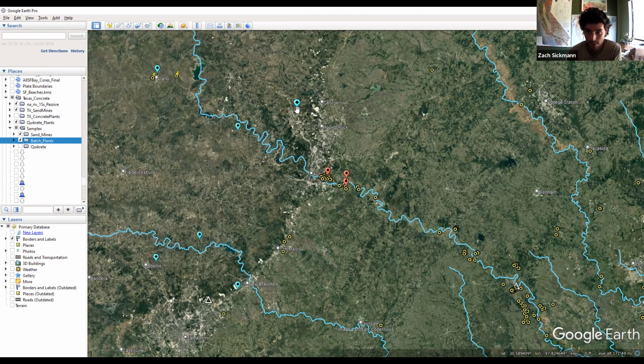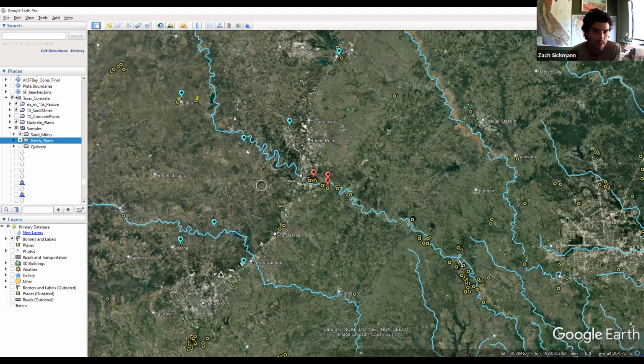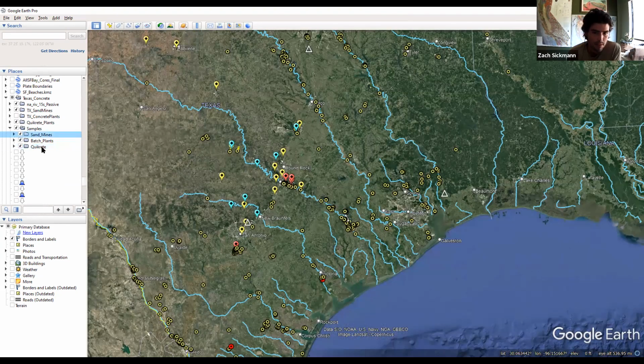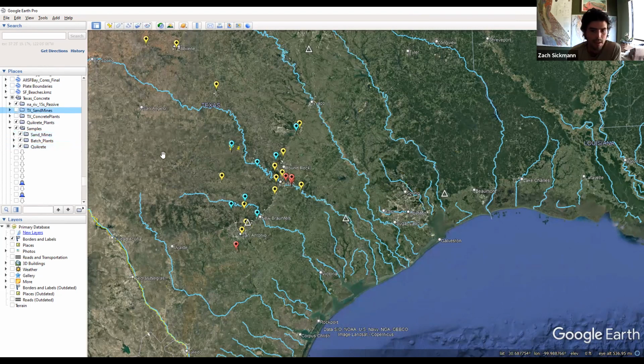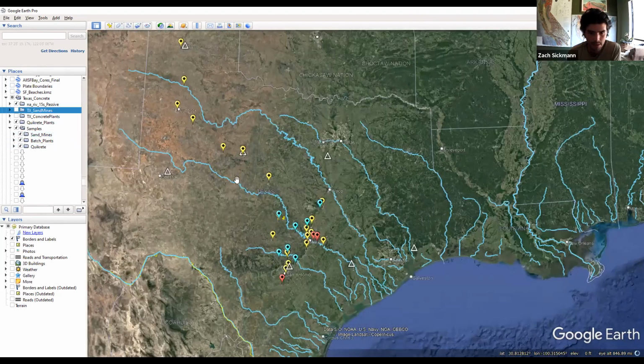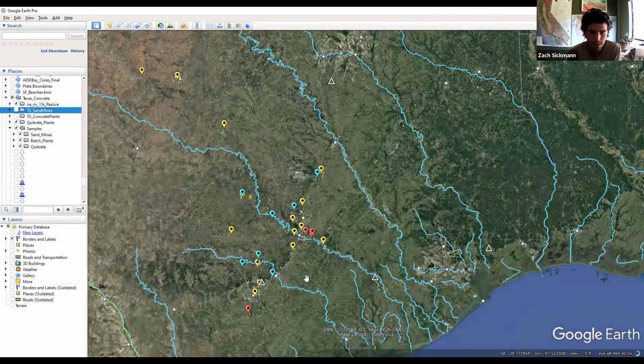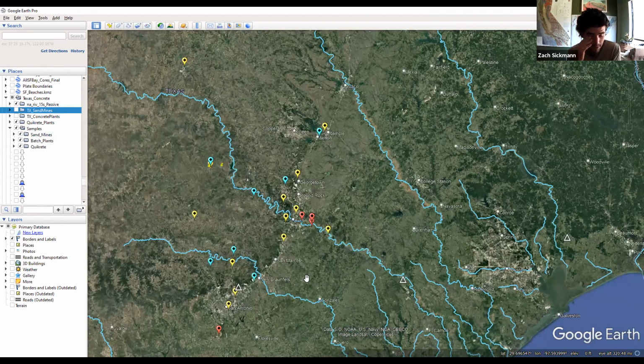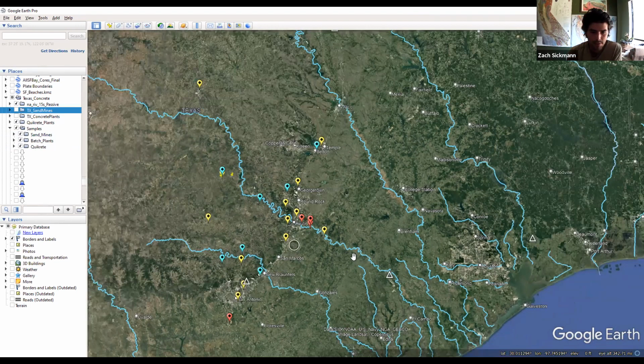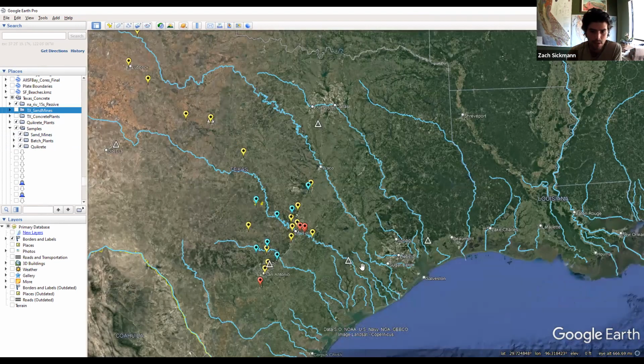And then to look at using these compositional signatures to define broader distribution networks, I went around, I'm going to turn these mines off. I went around to a bunch of hardware stores across the state and bought bags of concrete and washed the cement out, just poured it into a 5-gallon bucket and washed it with a hose until all the cement was gone. And then I'll show you what that looks like in a second, until just the sand was left. So doing that, you can basically define the boundaries between the distribution networks of the different Quikrete plants.